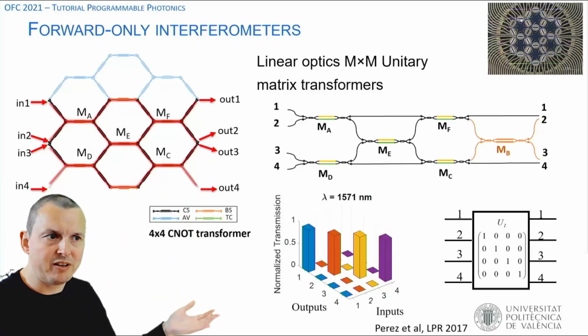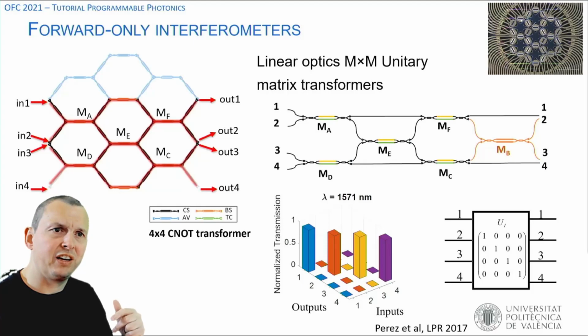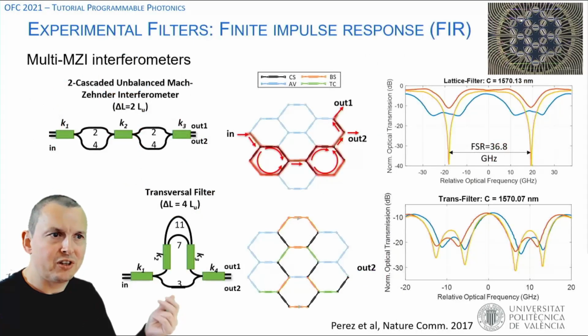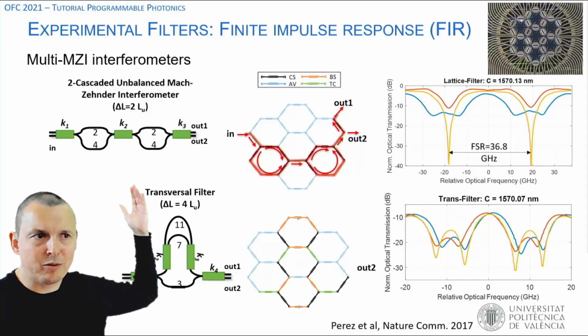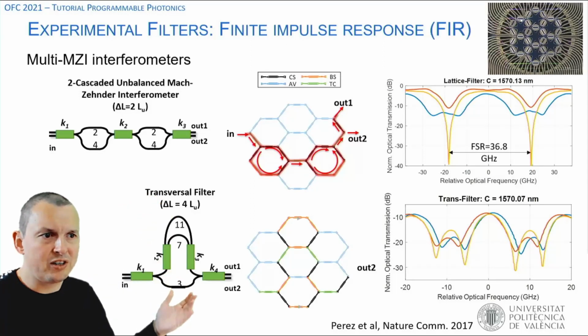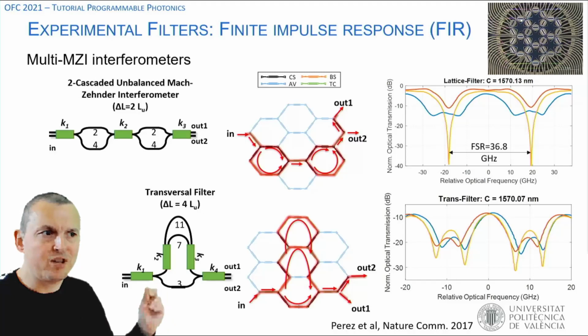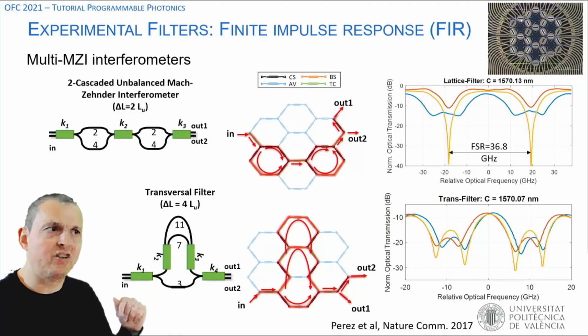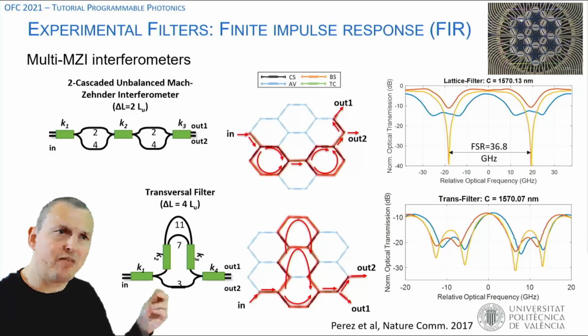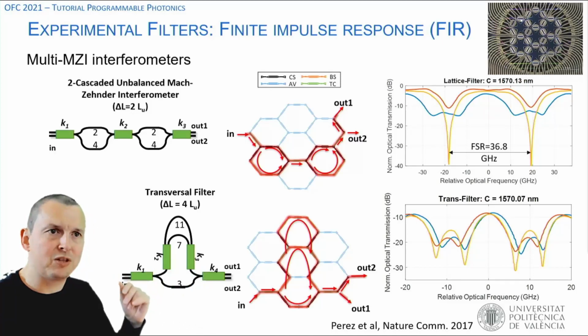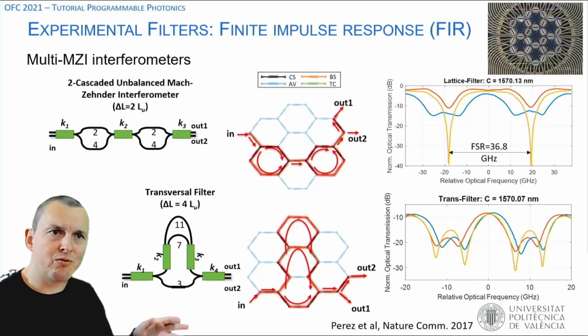For instance, implementing such a CNOT gate. But the most interesting functions are the filters. You can, for instance, construct this double Mach-Zehnder interferometer or this 3-path interferometer by just configuring the coupling sections. And because every coupling and phase is tunable, you can tune the actual filter response curve. And the same is true for ring resonators.